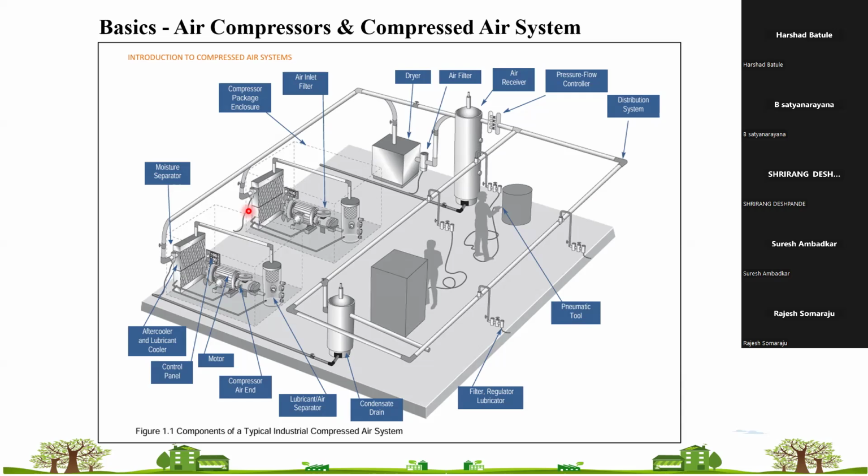So if your pressure is 6.1 bar, the compressor will sense that I am not in the actual requirement condition, so I'll start my work of compression. I'll deliver the required pressure. So it will generate 7 bar and deliver it. But if it is drained by your leakages, the compressor doesn't understand. It is a waste. So how to calculate that?